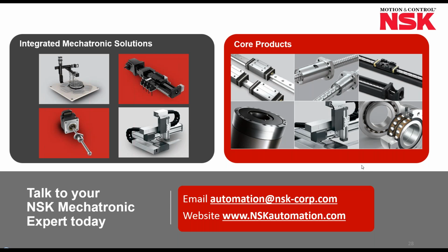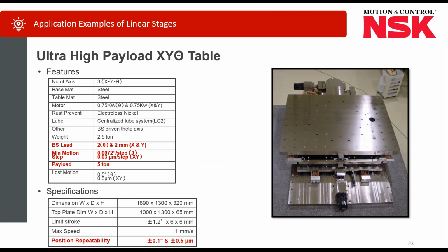And the all stainless steel XY theta table, how do you guys achieve the specs on something like that? Let me just look at it real quick. On that particular stage, I think what's most difficult about it are going to be the repeatability specifications. So repeatability of motion is commonly described as moving to the same position in the same direction. We call that unilateral positioning repeatability. So that means that we've essentially taken out the backlash of the ball screw and or motor as we're always moving to the same location in the same direction.